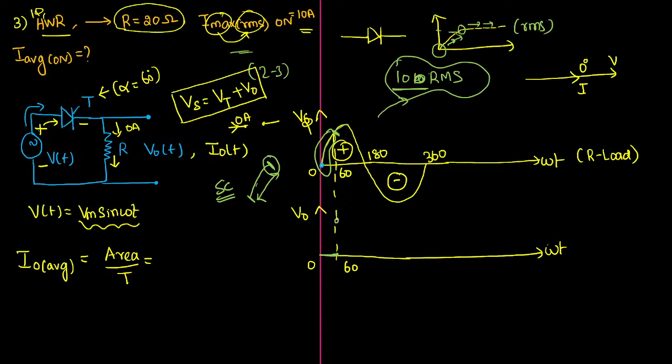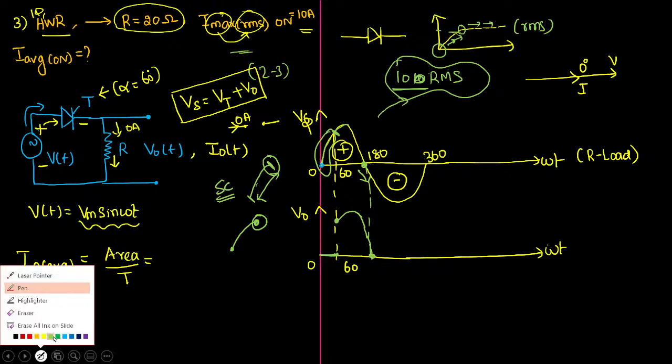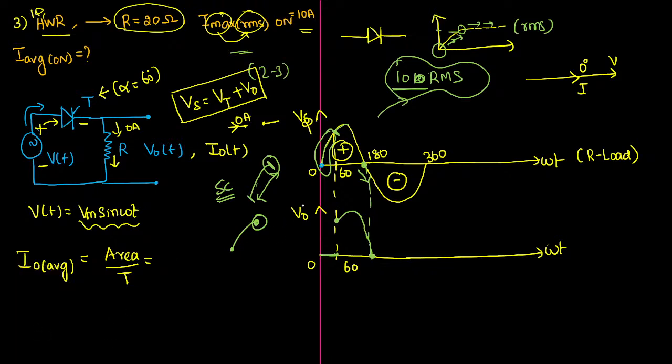Remaining portion means from where are we starting? Initially it was at 0 sinusoidal voltage, then at 60 degrees it has reached some point. From this point we have to start. The remaining voltage will start appearing across the output like this. But after that, the problem is when we enter the negative zone, since we have a resistive load, it will accept instantaneous changes.